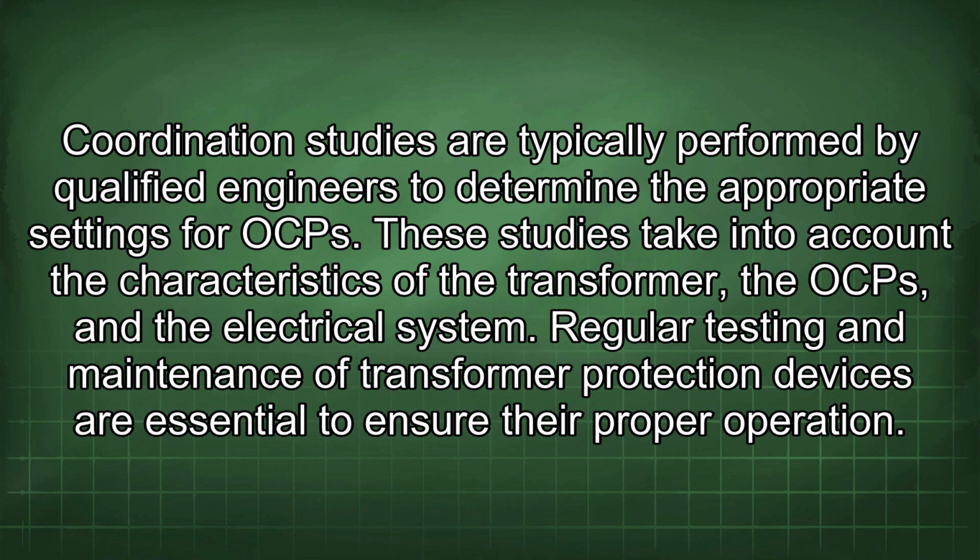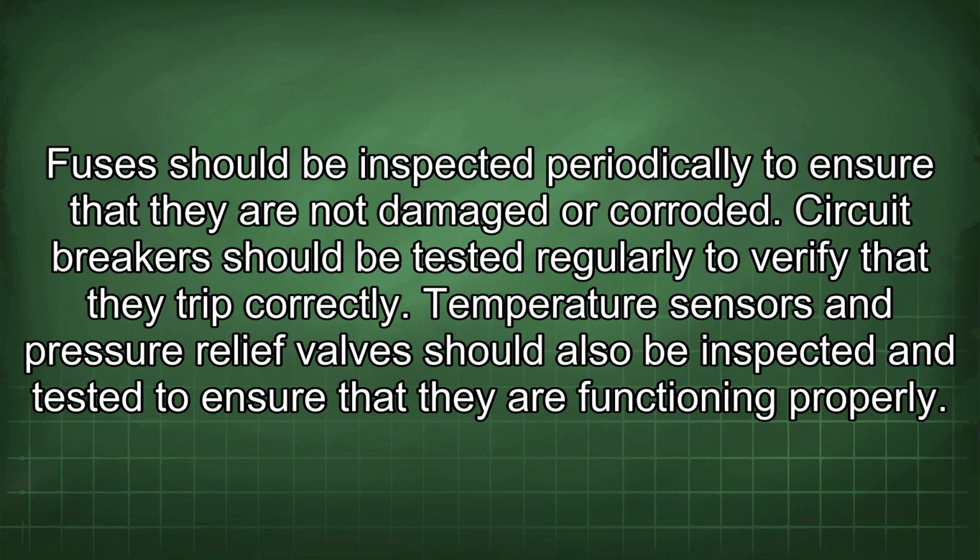Regular testing and maintenance of transformer protection devices are essential to ensure their proper operation. Fuses should be inspected periodically to ensure that they are not damaged or corroded. Circuit breakers should be tested regularly to verify that they trip correctly. Temperature sensors and pressure relief valves should also be inspected and tested to ensure that they are functioning properly.